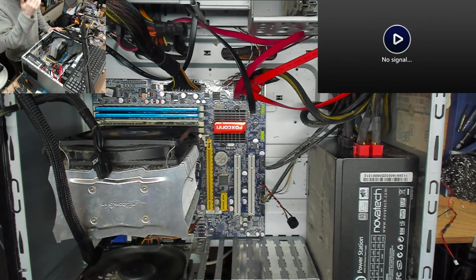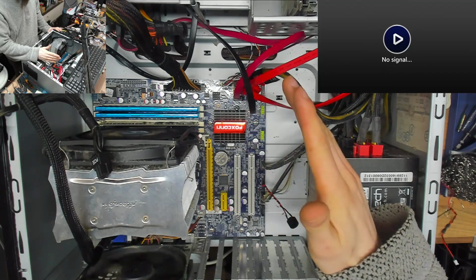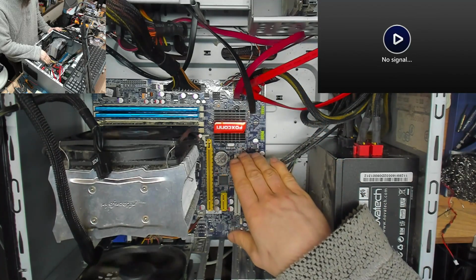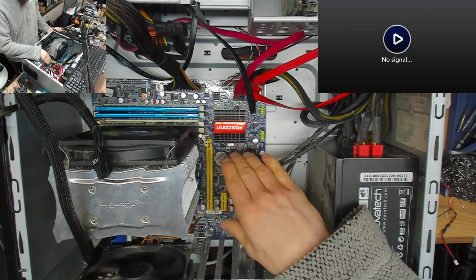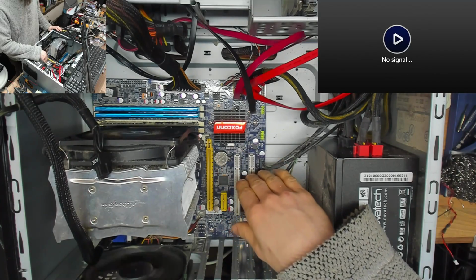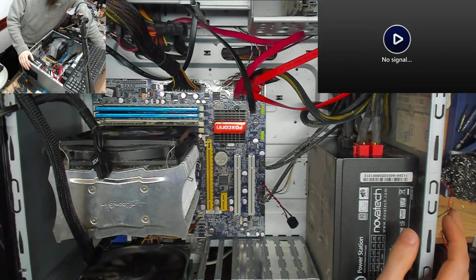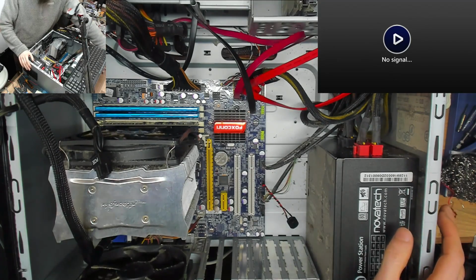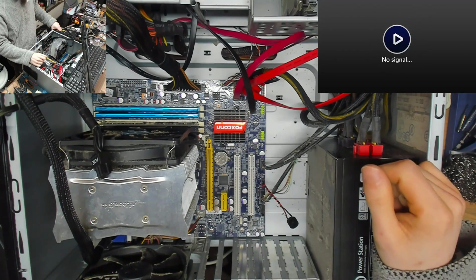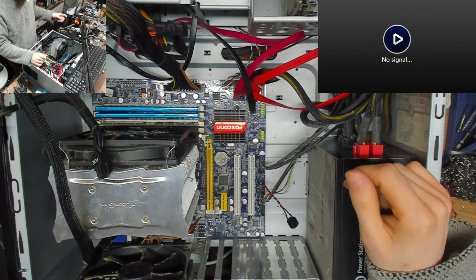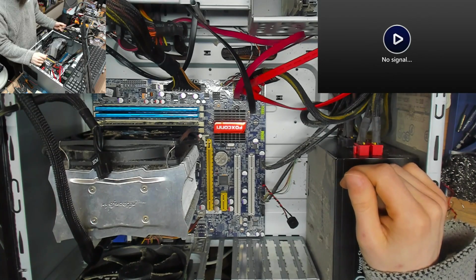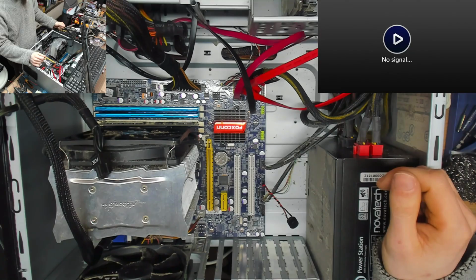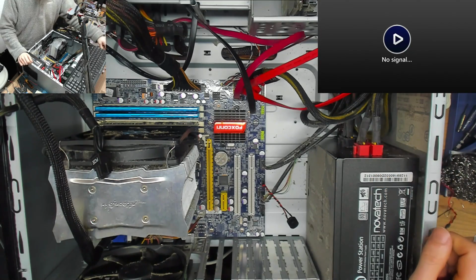Because after you switch off the power supply, it can actually take like 10 or 15 seconds before the 5-volt rail, the standby rail, turns off. And so that can sometimes upset systems. So let's just power cycle that one last time. And I'm going to spam the power button while the power supply is off just to try and drain that. The Antec gives quite a distinctive tick when the standby circuit turns off. Which it just ticked. Okay.